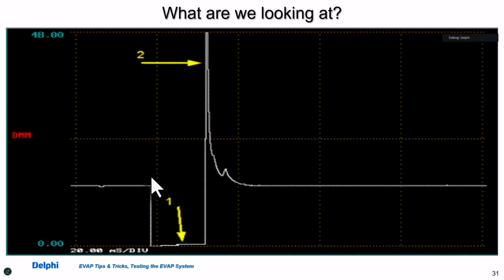So make sure that you realize you're working with a coil, and you could do current ramping, you could do scoping of it if it's in question. I'm not telling you to do this first, but if you have an unusual problem before changing a part, you might want to scope it real quick to see if the pattern looks something like this.